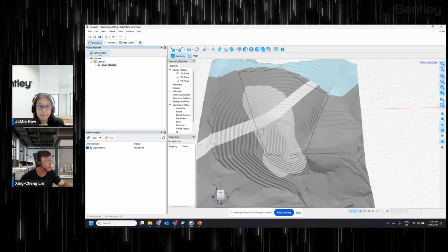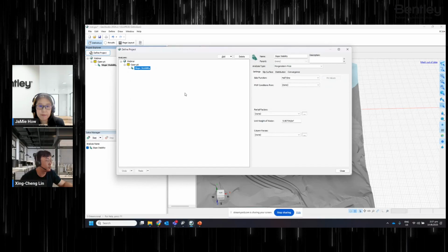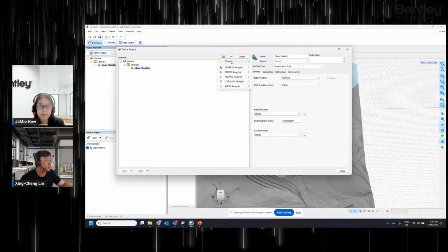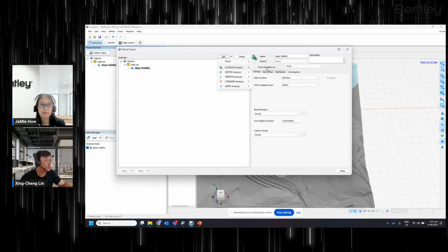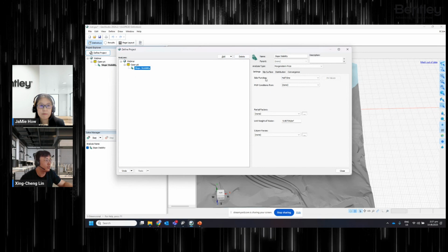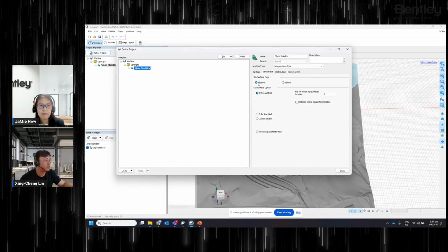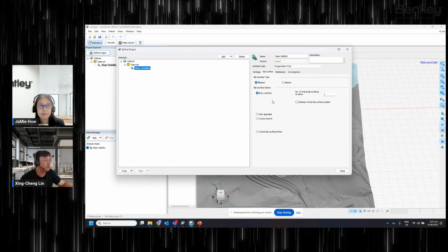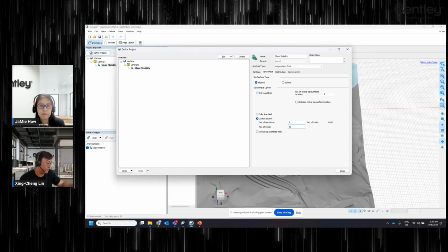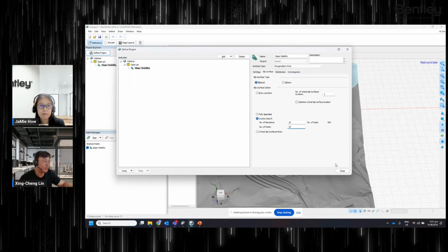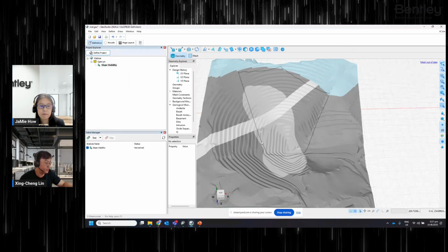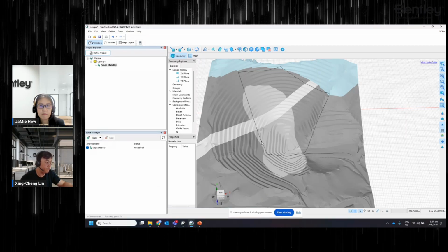In this case, we use the cuckoo search method. From the define project menu, you're going to add a slope 3D analysis. All right, I already have it here. So slip surface type, leave it as ellipsoid, and for the slip surface option go for cuckoo search. Define the number of iterations and number of nests. Right, so this is how we're going to come up with the definition.